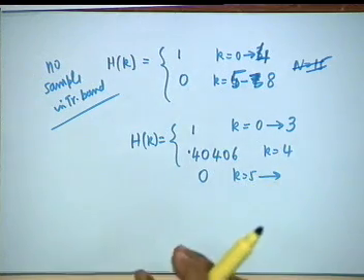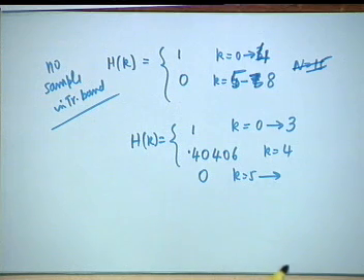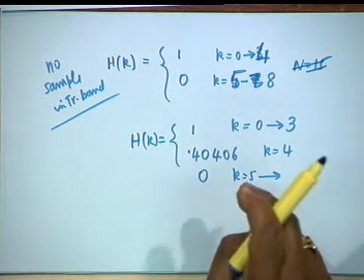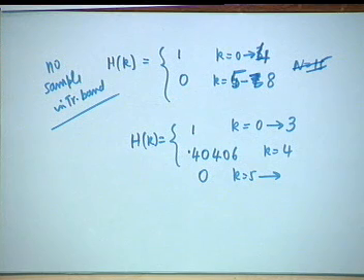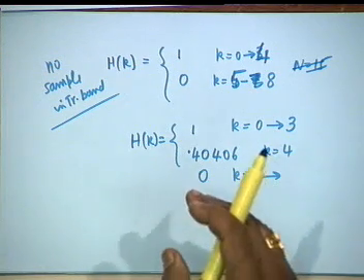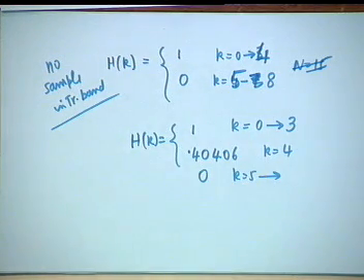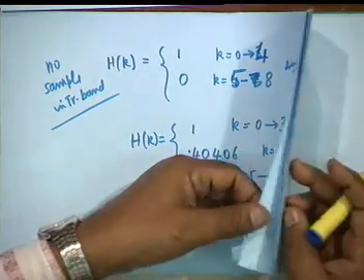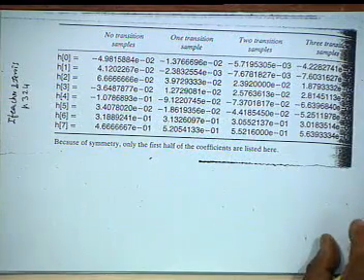So, if you use 2 samples, then in the linear fall the first sample in the transition band would be higher, the next one would be lower, okay. So, you can do this in a very simple manner, and I will only give you the final result. This has been calculated, and of the impulse response samples, only half of the number have to be calculated.